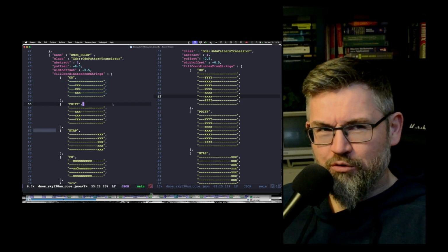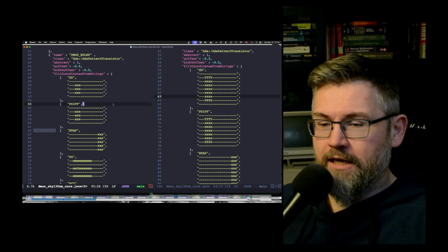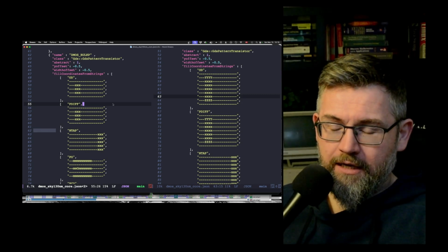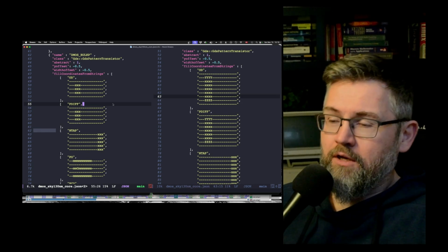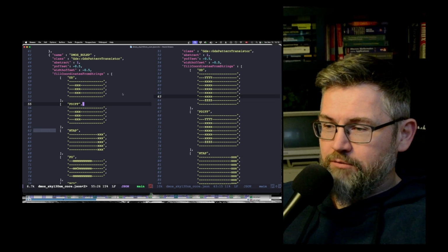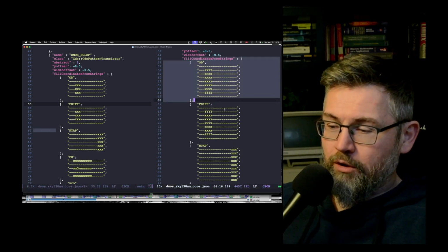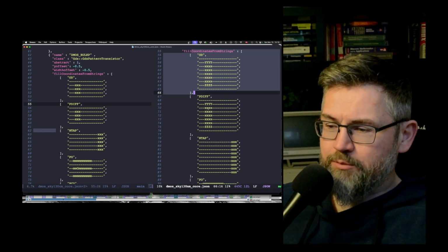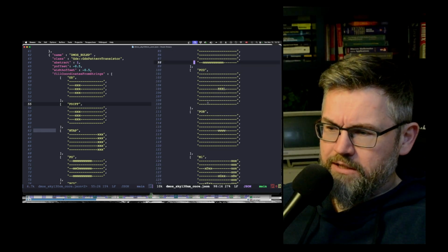It took some time to adapt to the style of Magic that has different p-taps and contacts for the poly and N transistor and so on. So that took some time to adapt to. And then the one on the right side is the IHP. This took less than a day to get DRC LVS clean.